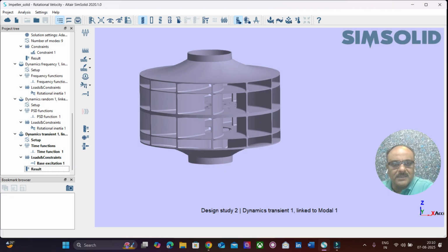So we decided to change the dimensions, the geometrical parameters of the system, and we changed the thicknesses of the members, the vertical members and the horizontal members. The vertical members, the blades or the vanes as we call them, and the horizontal members, the plates, the top and the bottom stiffeners, and the top and the bottom shrouds, and the top and the bottom crown, and then the central disc shroud, which was reinforced with two plates on either side and then bolted. So this was supposed to be a rigid system.